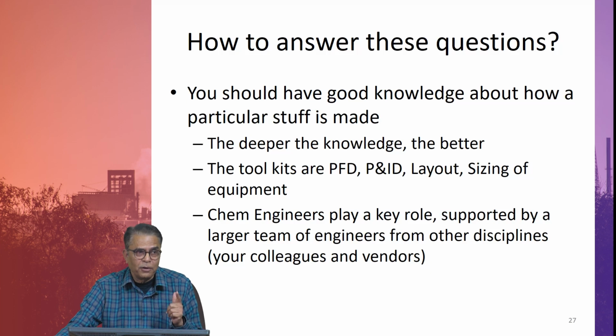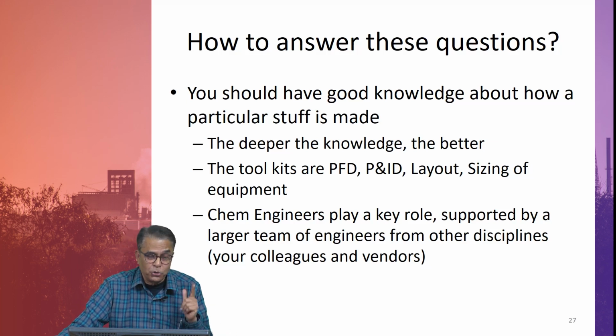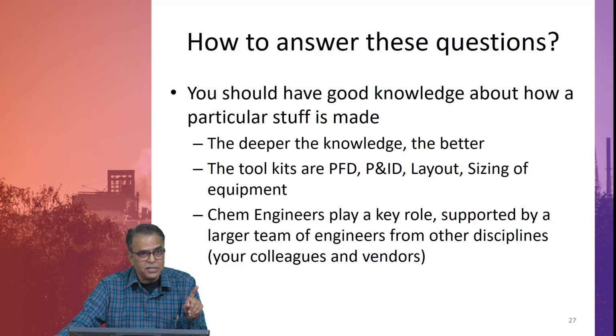because IPA is less dense than water, but you give with water. You know why? When it is going to be tested after completion, you will fill it up with water and do a hydro test. So, it should stand that. Of course, in running it will take solvent. So, this kind of detail the chemical engineer, process engineer provides, and the rest of the fellows jump in and put it in.